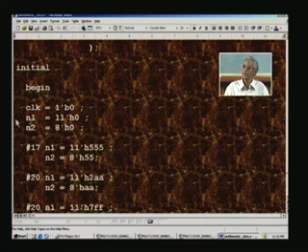We have an initial, that is a begin, and a final end. We stagger by a few nanoseconds, so that we apply the clock only after the data stabilizes. That is why, instead of 20 here, we need to put 17, so that the data is applied before the clock arrives at 20. That is the implication here.